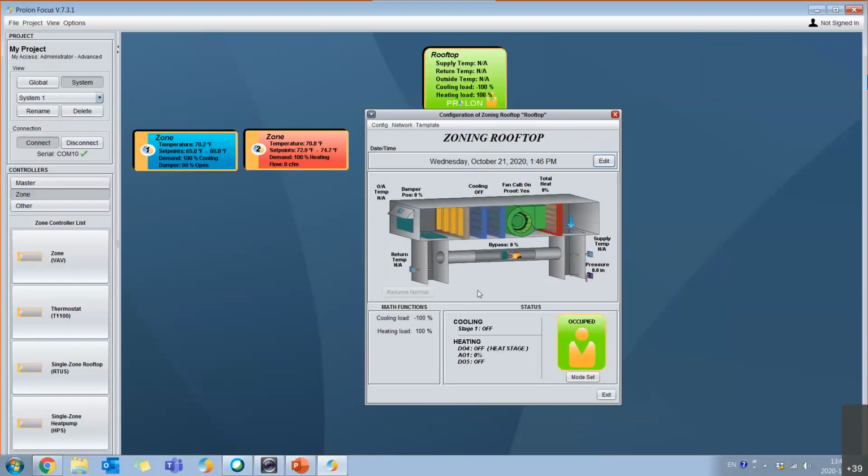Once we've satisfied the space enough to turn off the cooling outputs, only then will the unit switch into heating mode. The reason we defaulted it to prioritize cooling is that oftentimes zones might have another source of heat, whether there's a baseboard, a zone valve, or some other peripheral heating source.